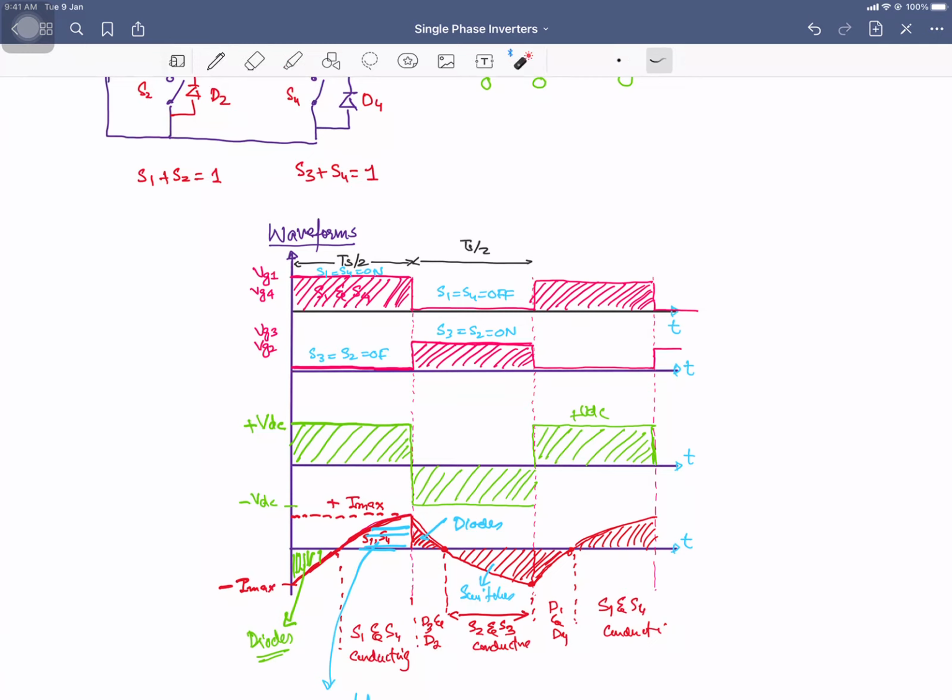So now you will have to turn on two switches S1 and S4 by applying the gate voltage, and when you apply the gate voltage, the load voltage will be plus VDC, right? So again, you can represent your inverter with a certain gain K, apply the gate voltages, and you get the load voltages, and we have the source, and whatever is the source voltage, that will be replicated across the load considering the ideal switches, and the wave shape will be of this gate voltage, right?